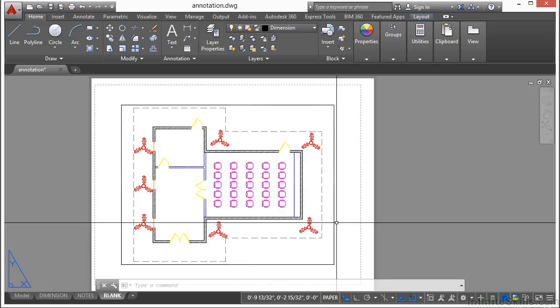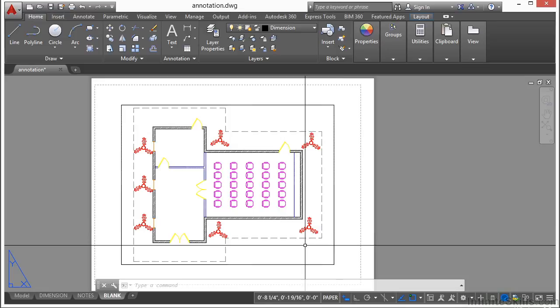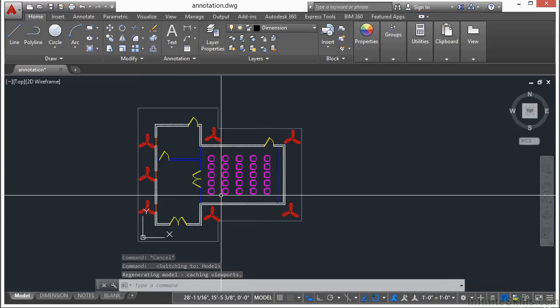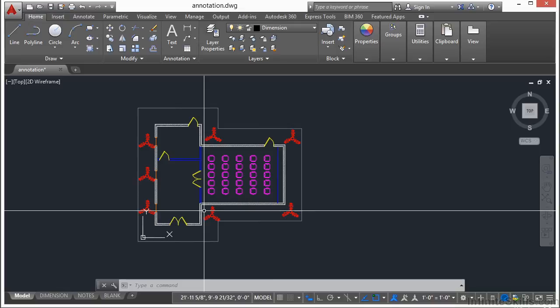You can also use it to explode a polyline to break that polyline up into its regular lines and arcs. You can also explode multi-line text, making each line of that text single-line text. Go to Model Space. Once you explode something, the objects can be edited outside of the block, leaving the other block instances in the file alone and unchanged. Other objects that can be exploded include dimensions, polylines, regions, etc.